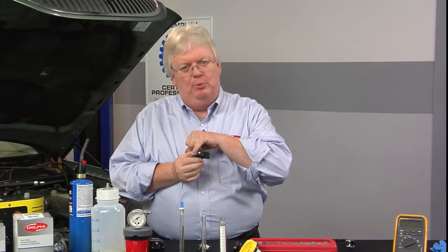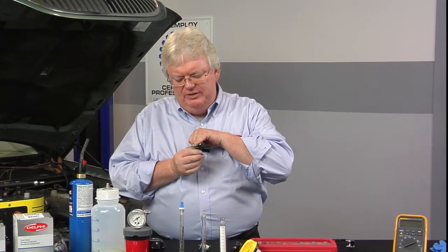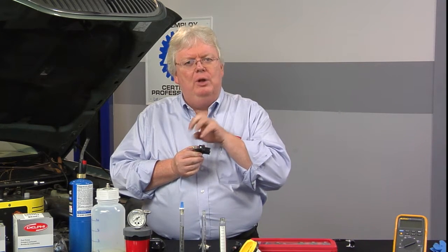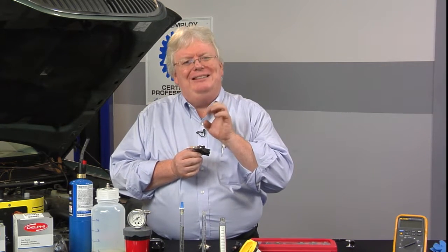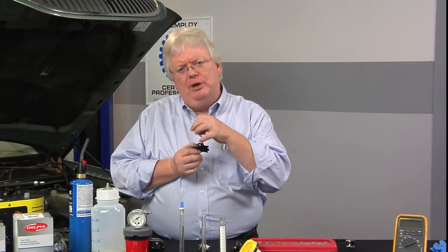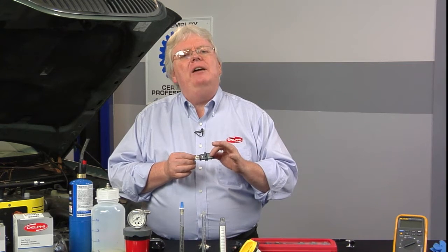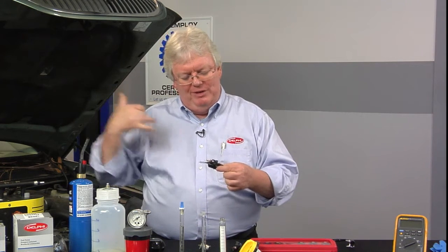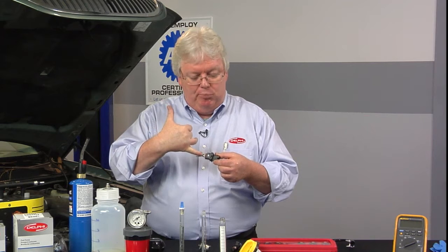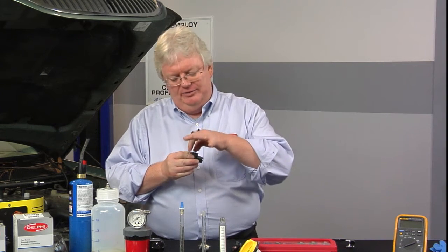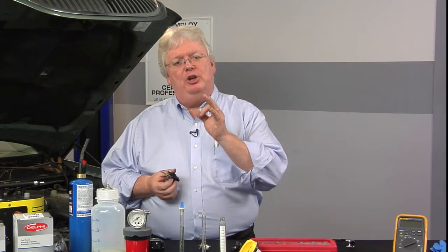You'll see a little circuit board, it looks like, right here. And what's in the middle of that circuit board is a little carbon resistor material that's etched or burnt with a laser, trimmed to just the right resistance value. These things are very complex, very fussy. You never back probe on this side of it because you could break that little board and cause that resistor to make this thing go out of kilter. When it does, it should set the code.